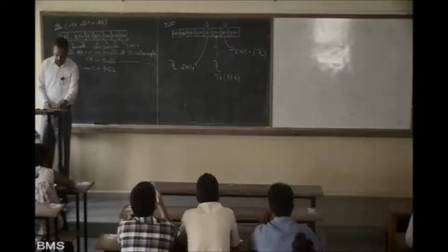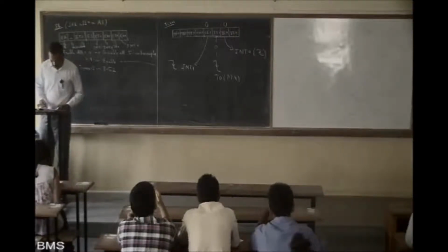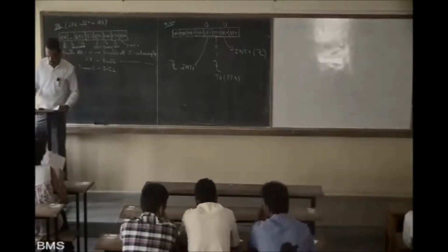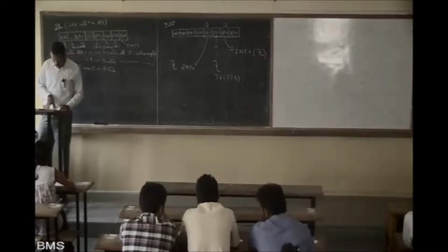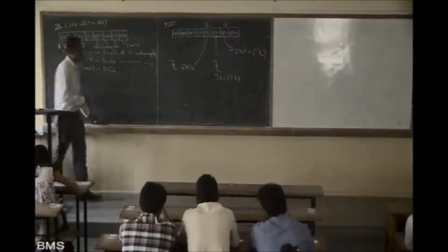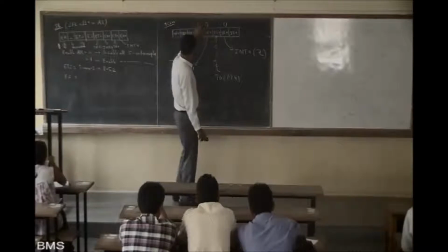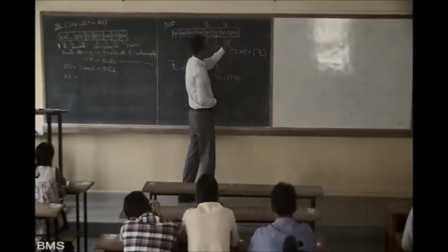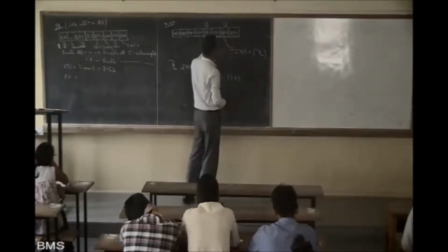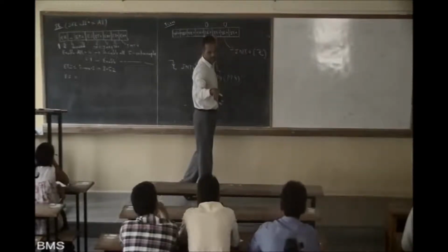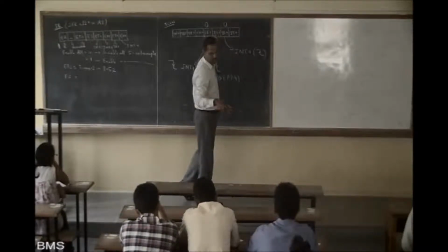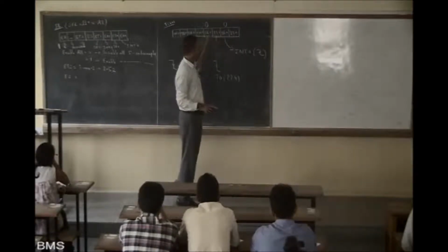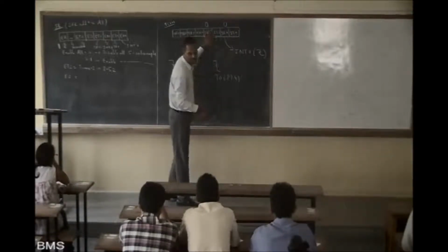Next, we have to write one small program very quickly. Shall I rub this part? Now, is this part clear? Any doubt in these 4 bits? IT1 for interrupt 1, IT0 for interrupt 0. This is a type setting bit, low level or edge. This is the edge flag. Whenever there is an edge, it will detect that. Clear with this?